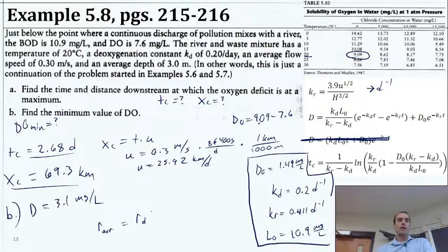And solving that out here, the rate of deoxygenation was KD L naught e to the minus KD t, right? And the rate of reaeration was simpler. This was KR D. Was this D naught or just a generic D? Just D. Drop this negative. Okay. Yeah, so when those rates are the same, we could then solve for D that way. Simpler. I like it. Would you use just the critical time? Yeah, you'd use the critical time there. This would only be for the case when those rates do equalize.